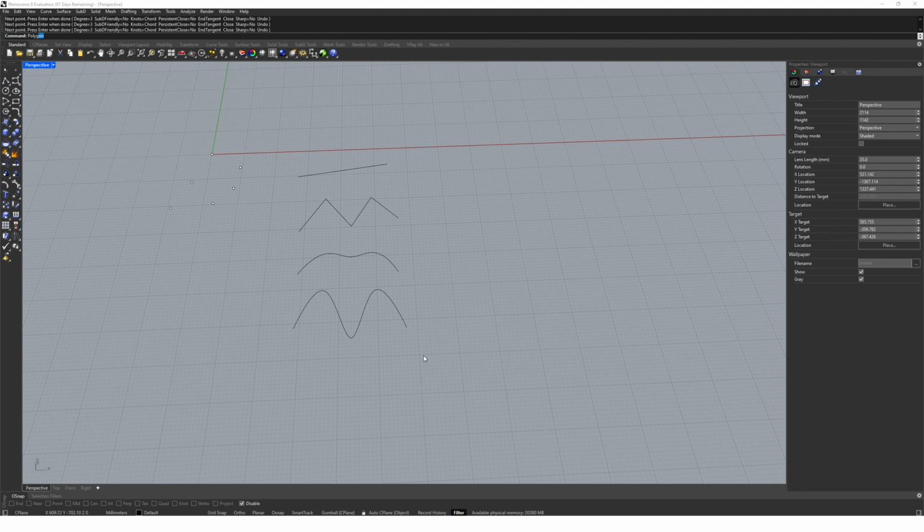We can also easily create polygons. So let's type in polygon, and I'm just going to create the standard one that I've got here, which is a hexagon. I'm going to click once and specify the radius. But if you remember, I talked about how you always want to watch the command line, and we can actually affect the type of polygon we're creating through this. So let's hit return, and we're going to now go up to the command line and change the number of sides to 5 to create a pentagon. So now I can click on screen, specify the radius, and I'll create a pentagon. So always watch that command line for options that you can change in your commands.